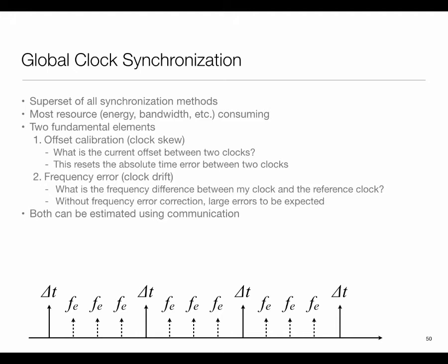For example, one approach might be the following. Once in a while, I measure the offset, and that I do by one of two approaches. Right at the very beginning, I can calibrate the delay, and after that point on, I can live off it. But let's say I haven't done it. So I have two arbitrary radios who come into each other's neighborhood. First thing they can do is a bunch of bidirectional exchanges, estimating the delay and the offset simultaneously. That's a costlier process. And then after that, they just try to keep their relative clock drift under control by one node sending out periodic messages to the other, the one-way stuff. So I can keep doing it until we realize, hey, our clocks must have drifted far enough apart.